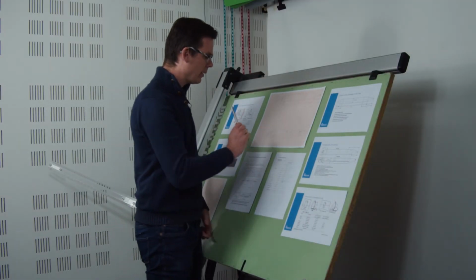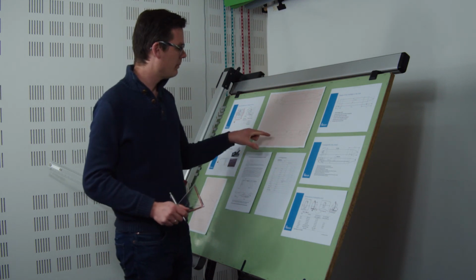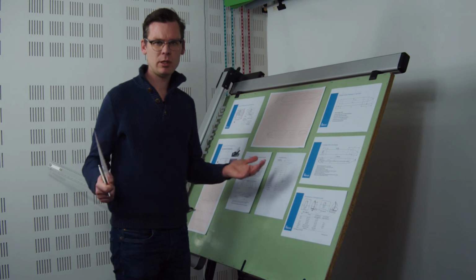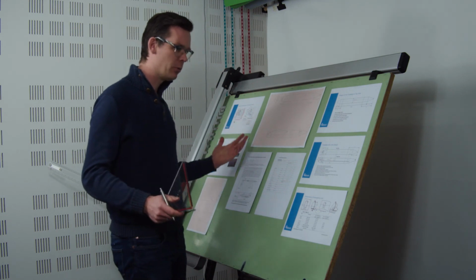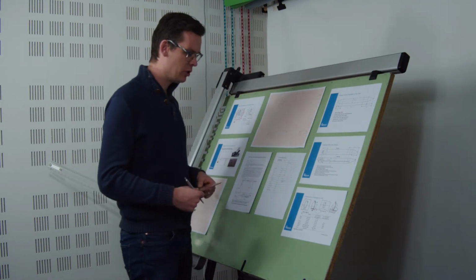Now the last one would be the type 1 exit in the front, but a little bit of interpretation here. Type 1 exit measures 1 meter 20, so it's about this high. So if you want to board and deboard passengers on a regular basis, which you typically do with a commercial airplane like this, 1.20 meters is not that tall. So for the main boarding door, I am deciding to use an oversized version. What the regulations state is basically the minimum size that you need for safely evacuating everybody. Now I'm taking a different standpoint: from a commercial point of view, I'd like a little bit bigger door. So I'm deciding to go for a Type A door, which is considerably larger.